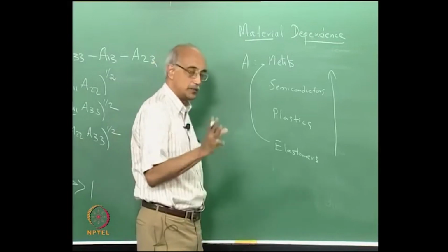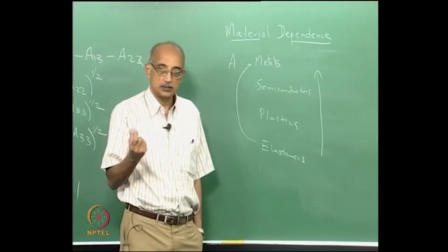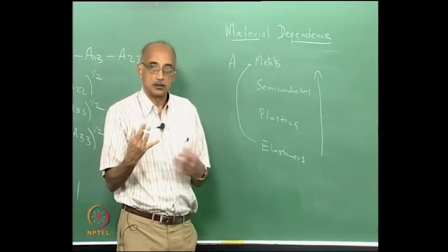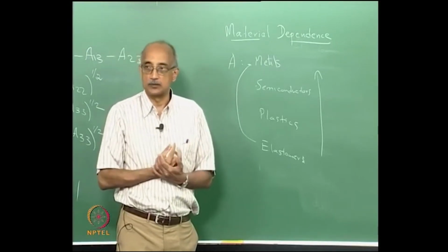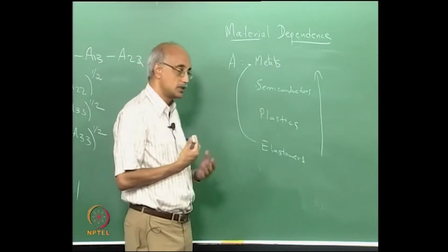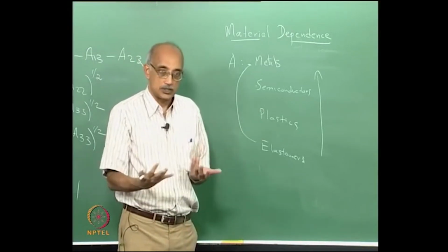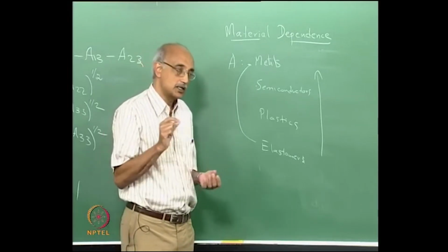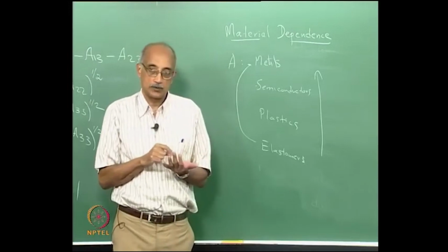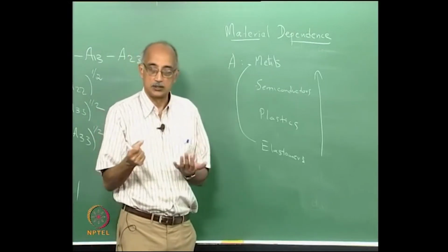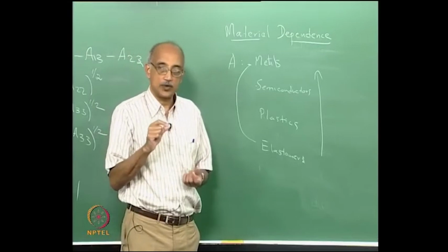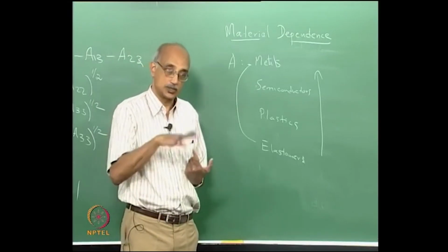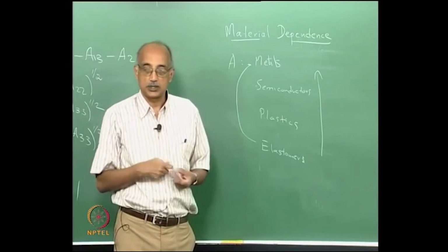So if you mold the plastic so that it is softer, essentially, you can actually make it less binding to the particle. So the use of, for example, composite structures is one way where you can accomplish it, although in many cases the composite material will actually increase the rigidity of the structure. So you have to design the system in such a way that whatever material you add as a composite actually reduces the hardness or surface energy of the material.